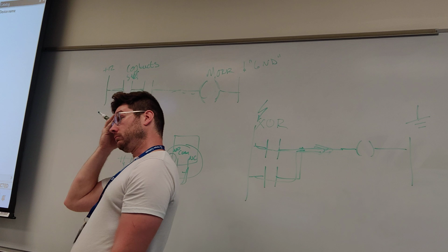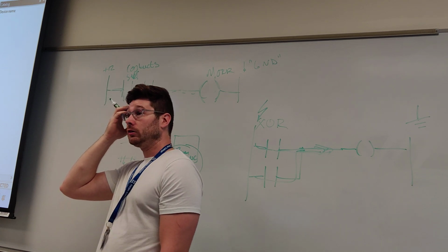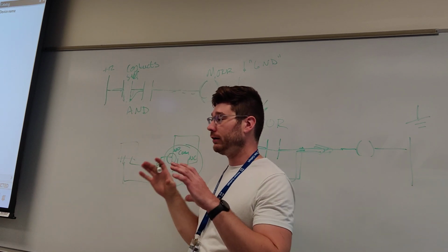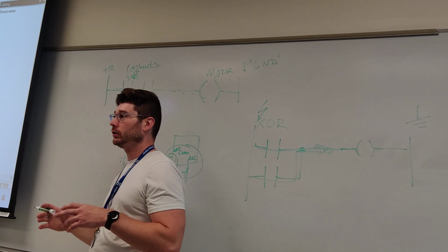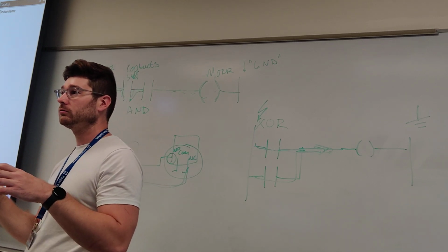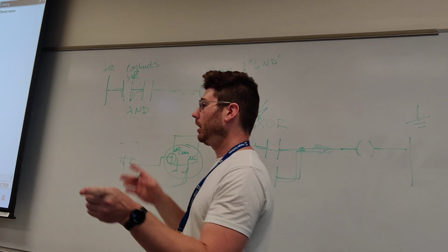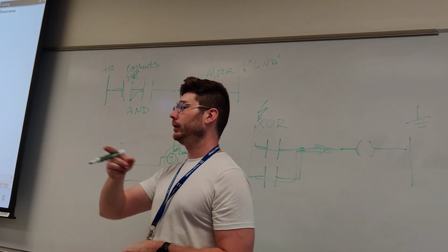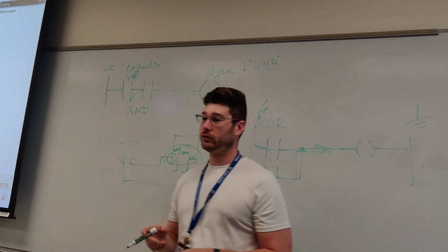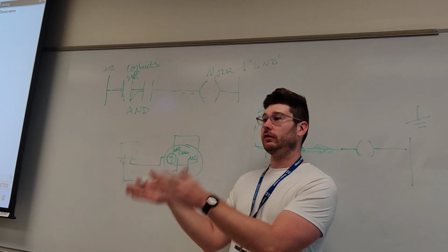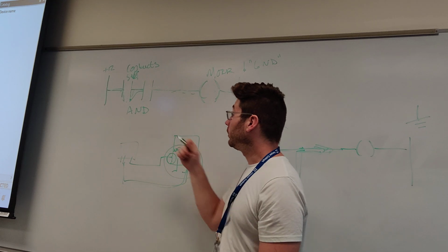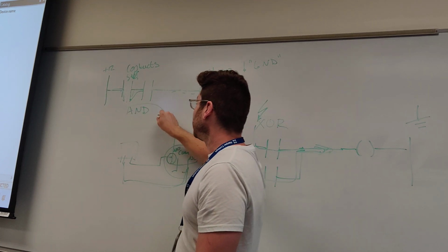The puzzle, the fun, if you will, comes from taking a paragraph of text that I give you or your boss gives you, implement this thing, solve this problem, fix this system, and making the ladder logic that directly implements the solution. If you say, when this thing happens, this other thing happens, you can implement that in one rung of your ladder.